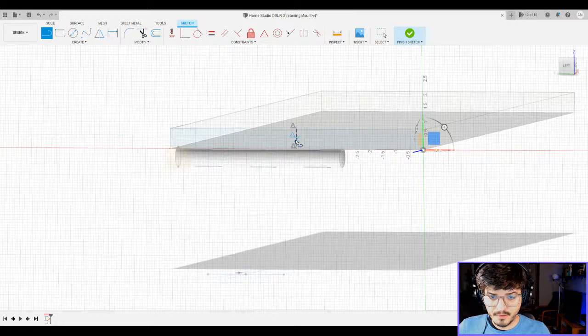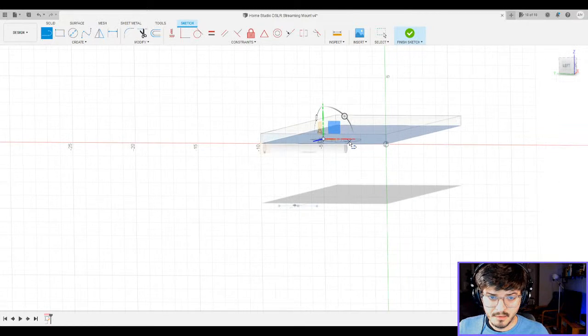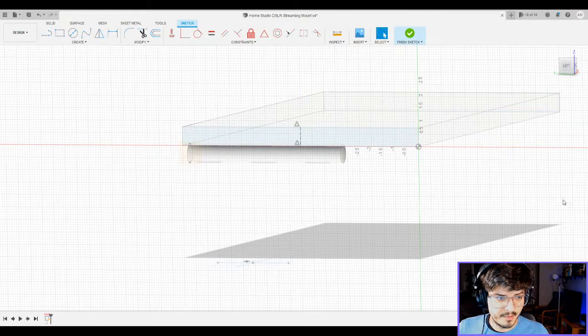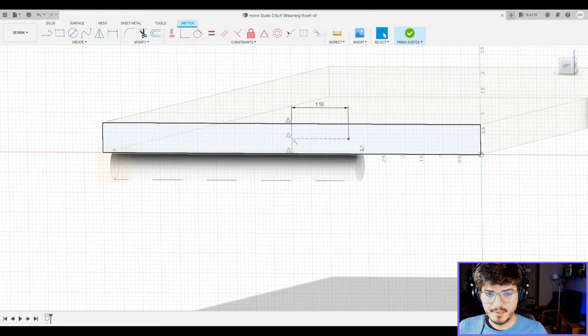We said it's going to be 3.5 inches, so I'm just going to pull up my drawing once more. So we said it's going to be 3 inches from center hole to center hole. Oh no, I do not want a 3D sketch, that's for sure. I'm going to do that again. And there we go. Constrain that, I'm going to have it 0.5 inches. Oh, I've got the wrong keyboard. Got it on English Canadian. There we go. Got that.